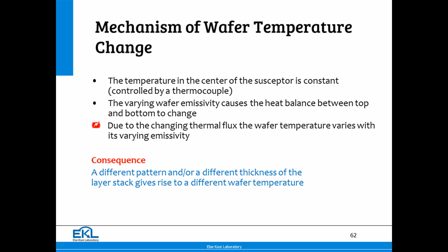Because that is the section where we are extremely sensitive to temperature variations. On top of that, at low temperature, more of the heat transfer is by conduction. At high temperatures, it's radiation, which is less sensitive to these kinds of effects. And of course, it only happens on patterned wafers, when we grow on oxide.